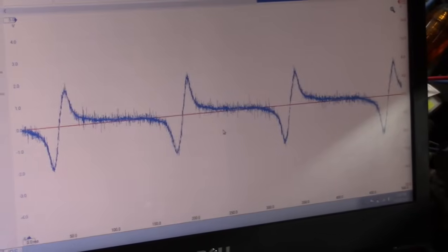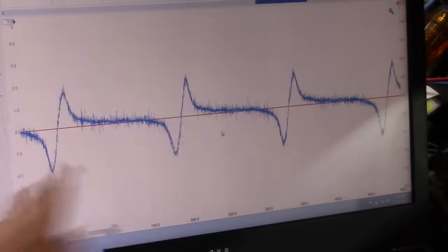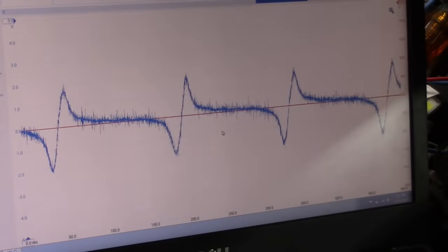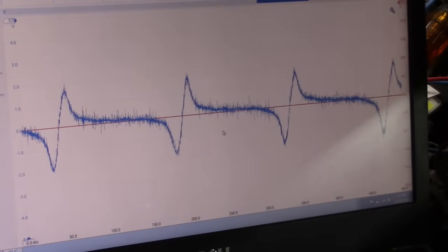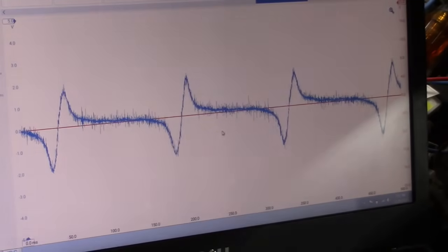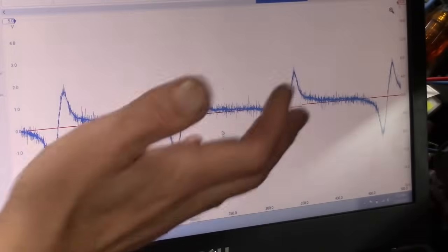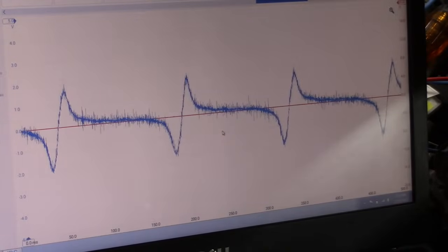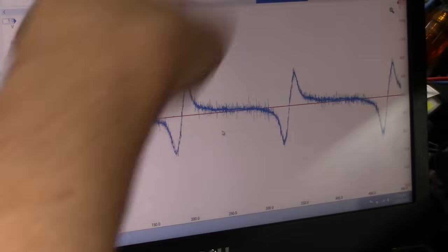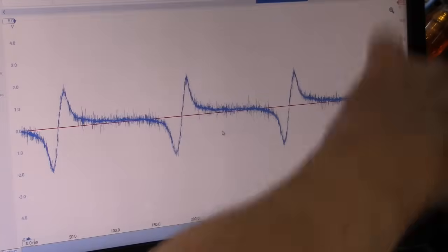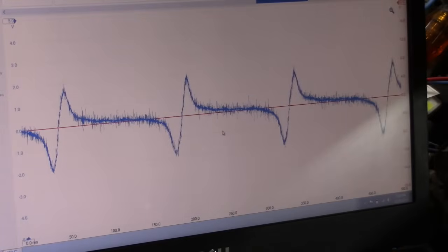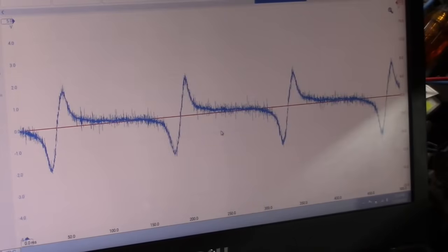All right, so looking at this, I do believe it's probably making sense, even though it's not exactly like I said earlier. In retrospect, this is a top dead center sensor. So it's only going to catch, I believe, on the top dead center positionings, as opposed to, say, a crankshaft position sensor where you would get, I expect, much more of the usual consistent sine wave. But that's definitely a specific signal, so we know that that's working. And of course, we knew it's working anyway. We have an ignition signal.